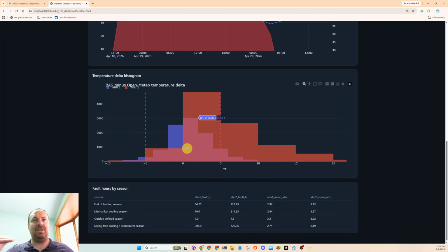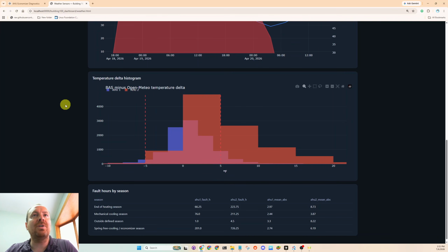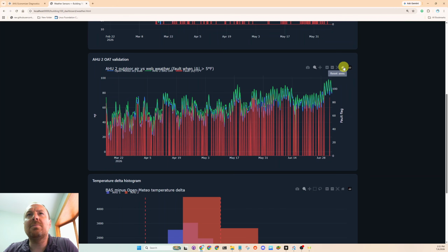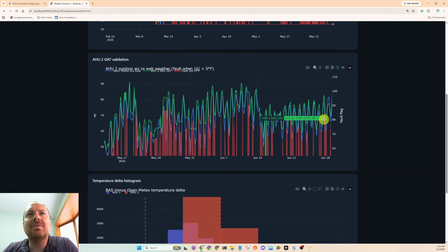Like you want the data to be a normal distribution. So if it's off by some scale continuously, that is what air handling unit 1 would represent. But when this is all shifted to the right like this, we would see generally that this air handling unit 2 outside air temperature sensor would read way warmer. Let's just see if we can see something as a general trend.